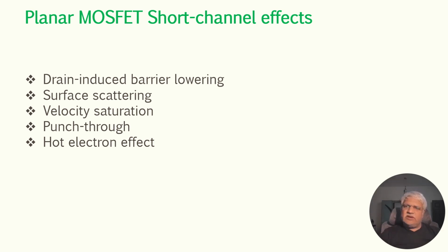Hence, when the gate is turned off, there is absolutely no gate leakage, and there is no drain to source leakage current. However, in 20 nanometer and below, as we discussed earlier, since the dimensions are reducing so much, the transistor performance was affected by the short channel effects.